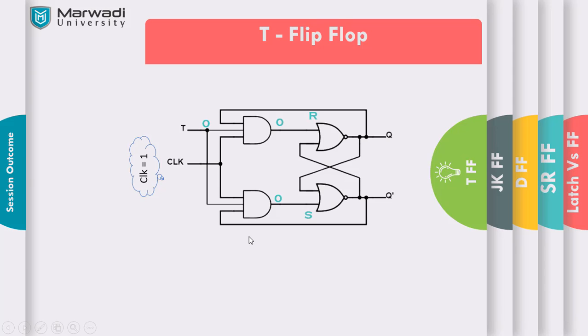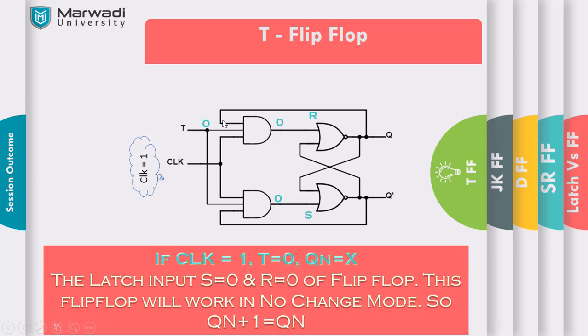So let's take the other input T and the different feedback outputs, but let's consider the first case, T equal to 0. Here if T equal to 0, this 0 will go to both AND gates. So again the AND gate does not depend upon the feedback input, because if one of the inputs of the AND gate is 0, output will be 0 for sure.